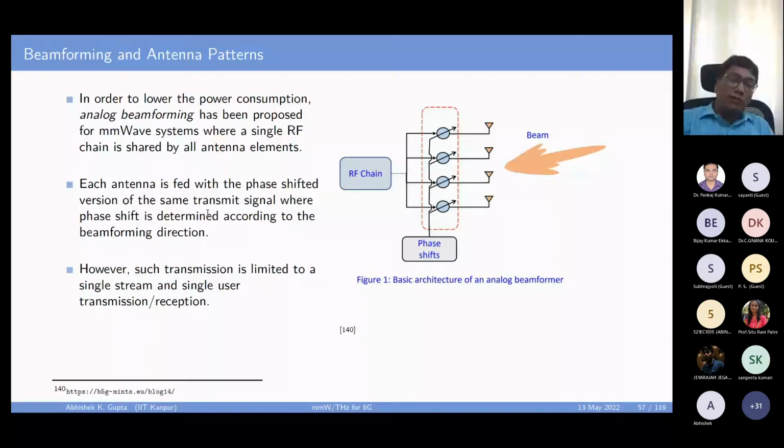So what we want to do is, instead of this digital beamforming, we move to analog beamforming. So in analog beamforming, what happens is these are different antennas. The signal comes in analog itself. They are multiplied by some phase shifters. So these are phase shifters. Each signal's phase is shifted and then combined together, and then that is passed through the RF chain to convert to the digital signal. Now, by varying the phase on these phase shifters, you can change the direction of receiving or transmitting. So this is known as analog beamforming, okay, and it is achieved by a phased array.